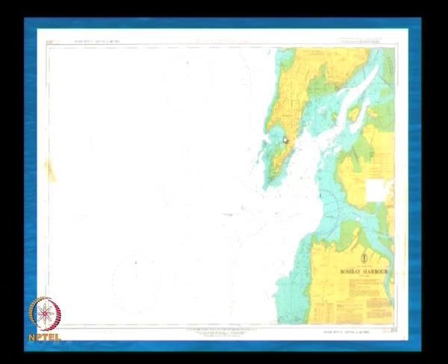The Bombay harbour is protected by Bombay island from the Arabian Sea, and JNPT is well protected. Elephant Island is also protecting it, and in addition the whole Bombay island is protecting JNPT. You have the navigation channel here, so you have to do the survey at very close intervals at these locations. The scale is also important, the scale at which you prepare the survey.